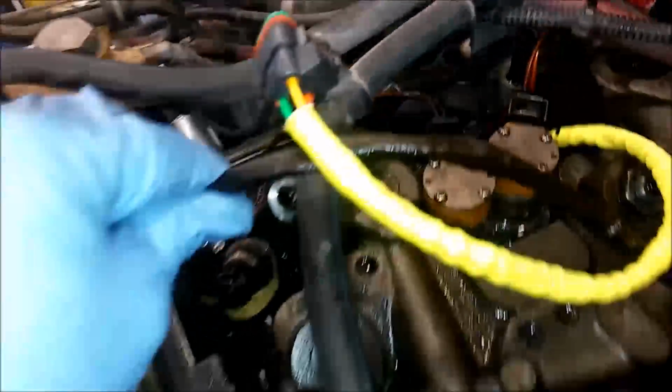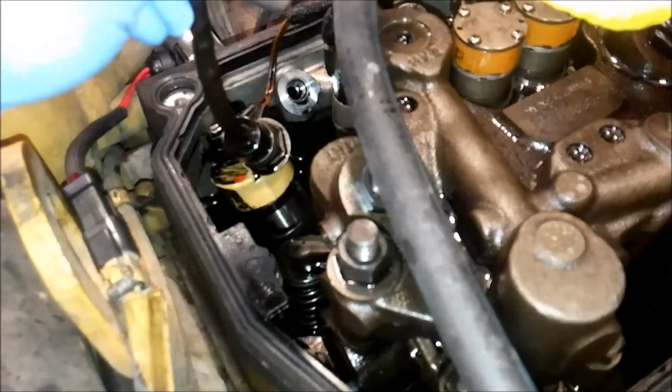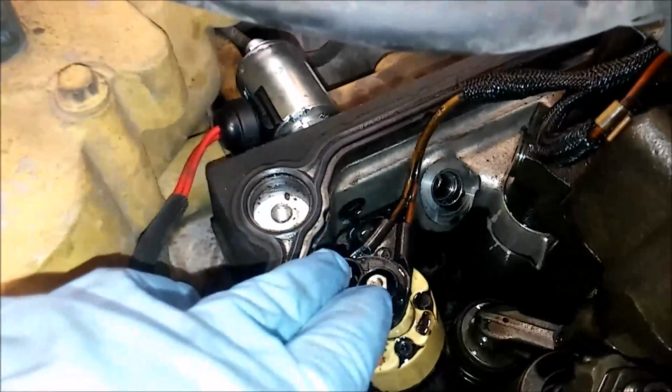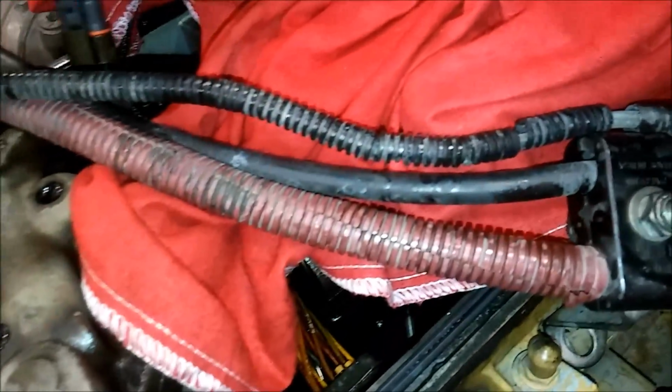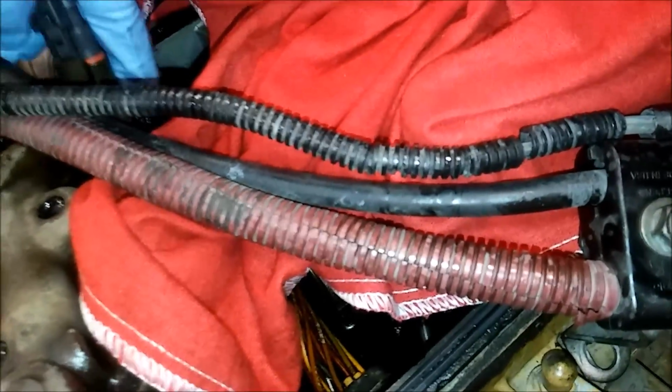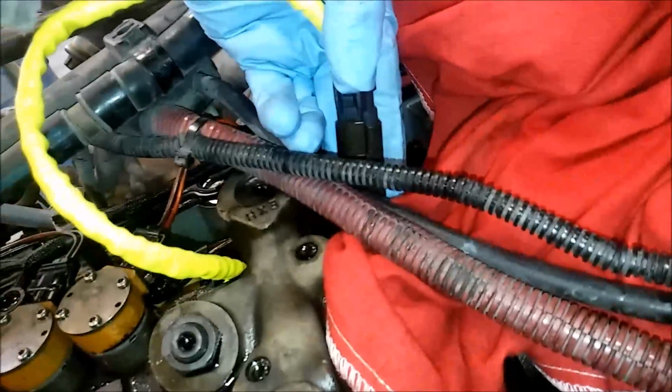In the next clip, we're going to be showing you how to troubleshoot solenoids like the injectors and the IVAs. But to finish this one up, you're going to remove your old sensor, our IVA sensor, and then you're going to get your new sensor, and you're going to plug it in. And you want to plug it in and make sure the code goes away first before you install it.